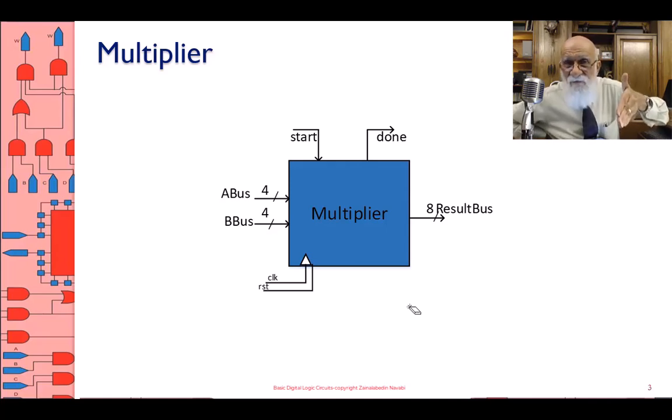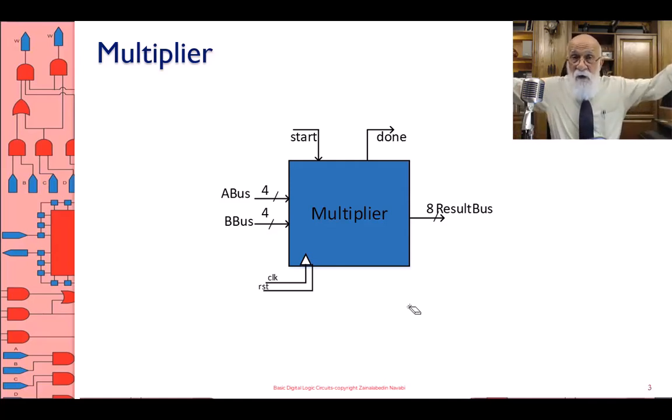For a 64-bit multiplication, if my operands are 64 bits, I use 65,000 clock cycles for performing this multiplication. True, I save a lot of hardware as compared to the combinational multiplication, but then 65,000 clock cycles for a multiplication.